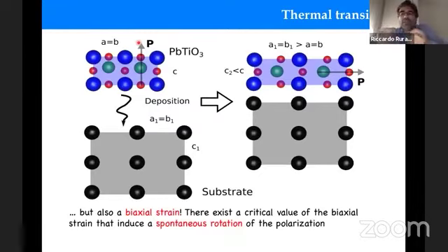If I strain the lead-titanium lattice, because I grow it on a mismatched substrate, if the strain is sufficient, the polarization will be in plane. Now imagine that I strain it sufficiently so that it's really on the verge of the rotation, but it hasn't rotated yet. If I strain a little bit more, it will rotate. If I am there, practically you can rotate the polarization in an effortless way, because it's just about to rotate because of the strain. So you only need a very tiny electric field to make it happen, okay?